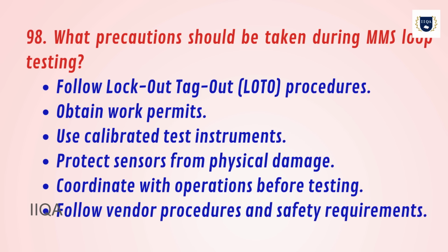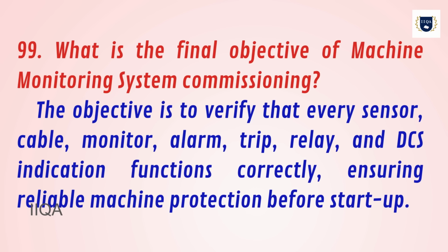98. What precautions should be taken during MMS loop testing? Follow lockout tagout (LOTO) procedures. Obtain work permits. Use calibrated test instruments. Protect sensors from physical damage. Coordinate with operations before testing. Follow vendor procedures and safety requirements.